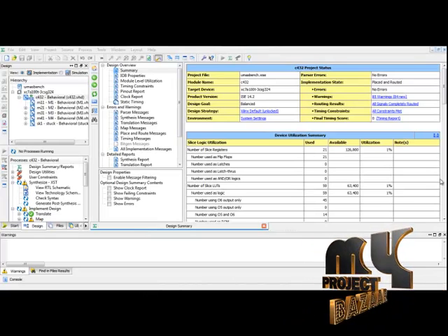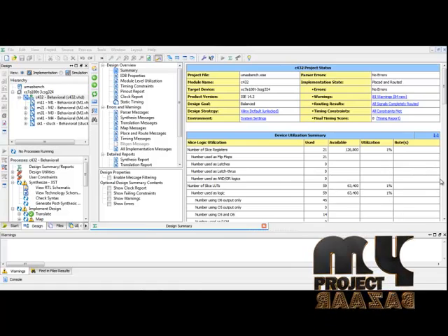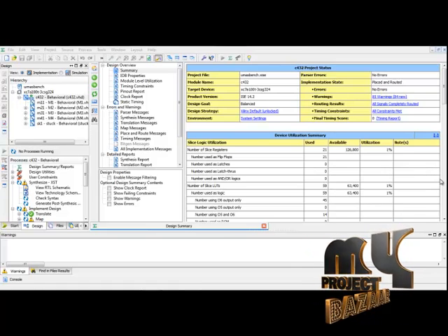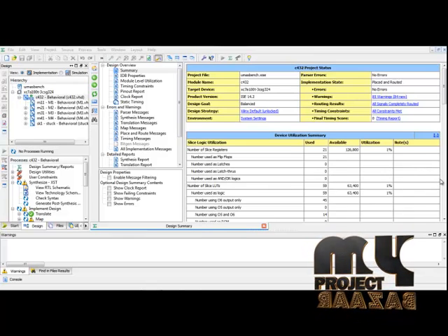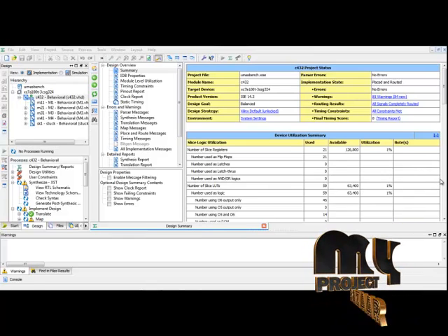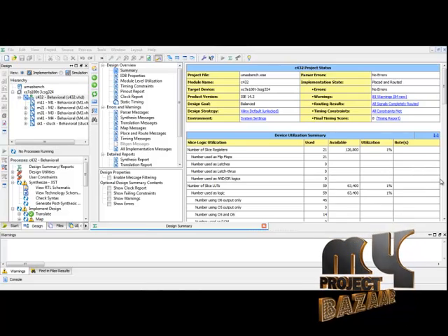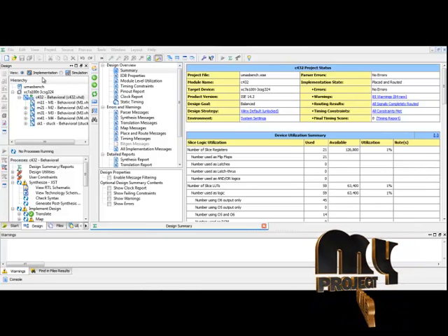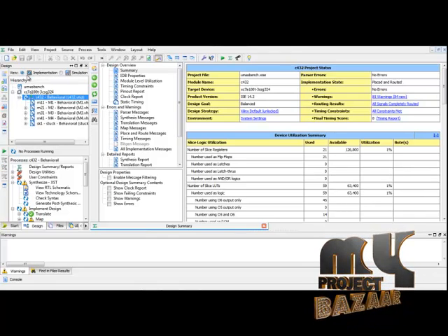Now we are going to discuss the running procedure of our project. In this process we have 4 steps. First step, we check the syntax error; second step, we generate the RTL schematic diagram; third step, we generate the technology schematic diagram; then finally we generate the simulation waveform. First we select the implementation. Now we are going to the first step.